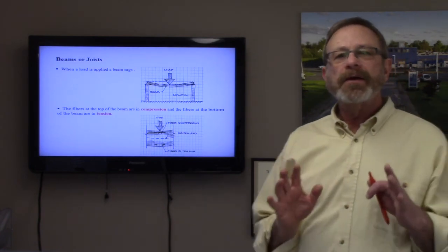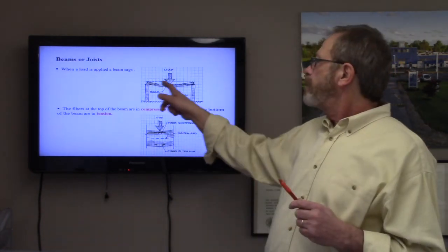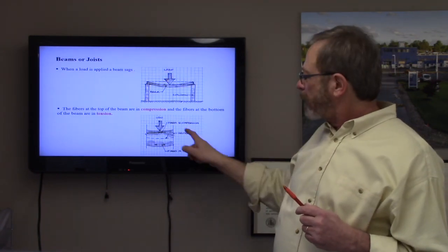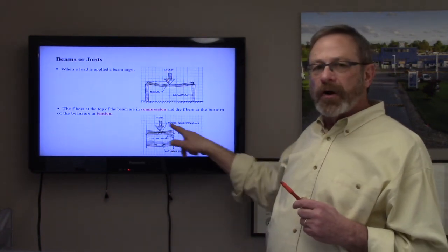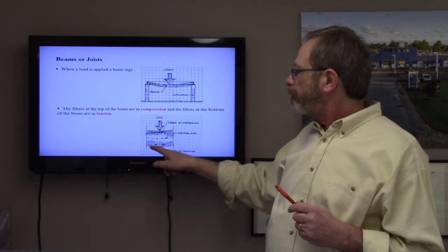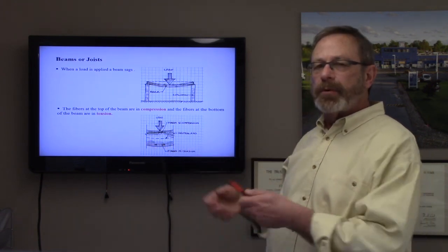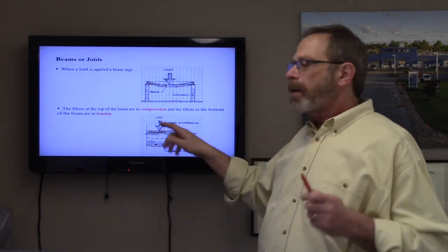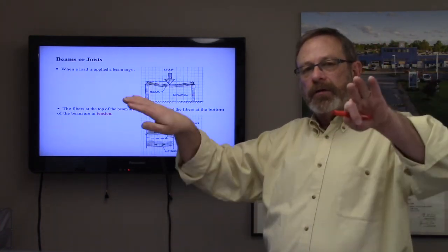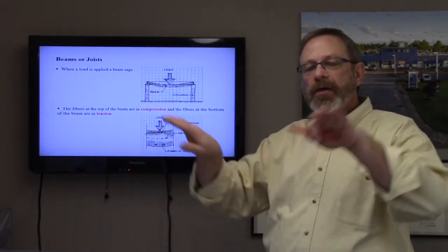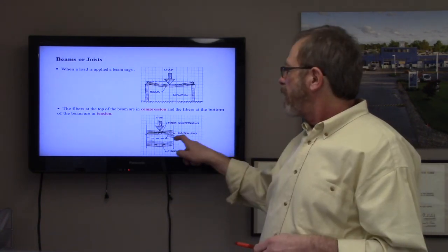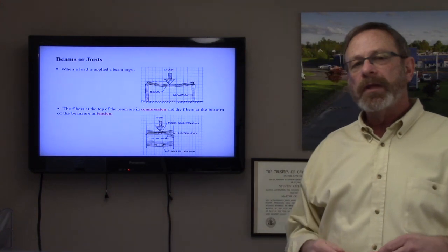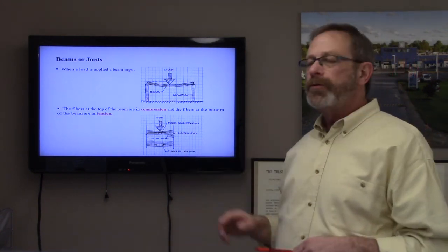So if you can imagine, because I don't have an example of this, a beam between two columns with a load exerted on it, and a magnification, these forces are like this: the bottom fibers are being pulled apart in tension. The upper fibers are being compressed together as it's bent. And in the center, those forces equalize, and that's where we have something called the neutral axis.